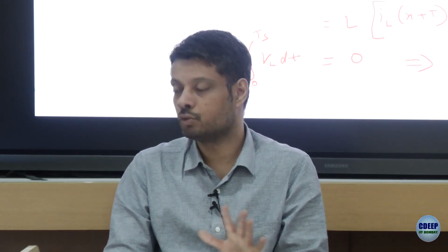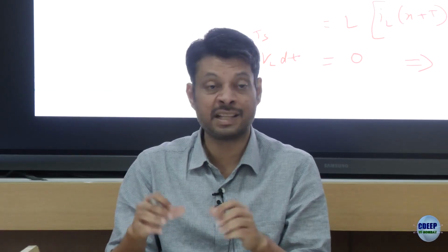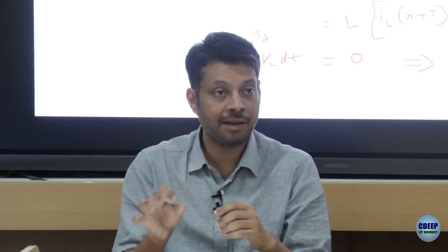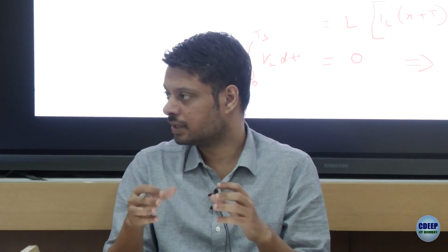Okay. So remember two things. This is the volt second balance. It's applicable if it's an ideal inductor, first of all, right? If there's a small r in it, that R plus L together will not follow this law. Only the pure L part of it will follow this law. That is one part of it.